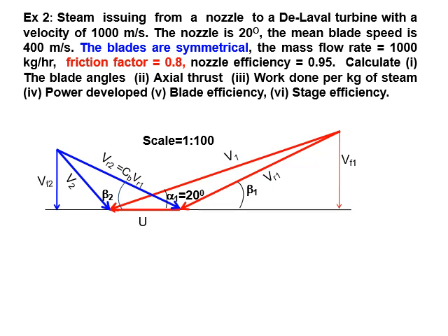Then measure the length of delta VU, or change in tangential velocity. Change in tangential velocity is equal to VU1 plus VU2. Now also measure the alpha 2 angle as well as delta VF, the difference of heights in the VF1 line and the VF2 line.